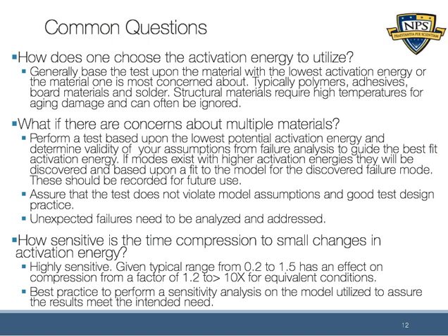And that really answers the second question as well. If there are multiple materials, you would choose the one with the lowest activation energy. But that would depend if it's multiple materials and they're in different parts. The only thing to be careful of there, because we typically assume that a part sees all the same temperatures, is if you have a part in one section of your system and a part in a different section, and for whatever reason you're comparing those, it's important to understand that some of the other variables in the Arrhenius equation could change.